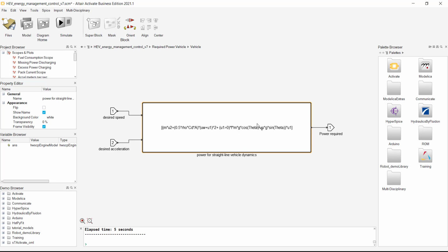And then this third entry is the frictional calculation, the rolling friction. And then the extra effort it'll take to take into account the incline of the road, the gradient of the road. So all of that will output our force required in order to maintain our desired speed.